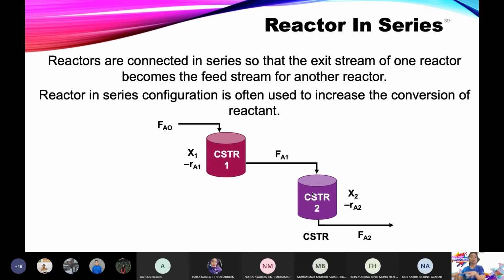Then entering the second reactor, the conversion does not start again from zero. The conversion starts from what you already achieved in the first reactor, which is 40%. Because we calculate the remaining 60 from the first reactor entering the second reactor. So the conversion in the second reactor naturally goes from 40% to 60%. Let's say if you think it is still low, you go to the next reactor, and you hope that from 60% it goes to 100% or 80%, and so on and so forth.